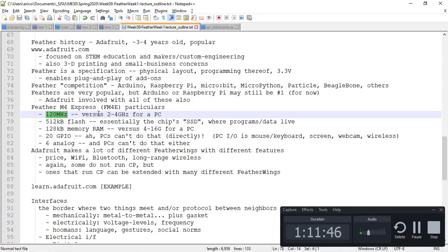You cannot capture the image data from an image sensor and store it in RAM inside of a microcontroller. The best you can do is read it line by line and send it out to something else, like maybe a connected SD card or over a network connection. But not only can you not read a high resolution picture, you just don't have the space to even read it, not to mention process it.